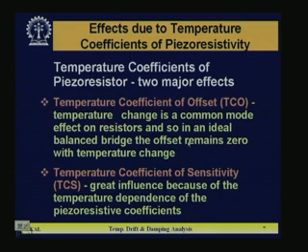Now, the offset is coming for what reason? All the 4 bridges we found there are total 8 resistances, and we assume that under no stress condition all the resistances of the 4 bridges will be the same. So, output voltage will be 0, the bridge is perfectly balanced. That is in ideal condition, but in practice all the resistances will not be the same. Even if they are the same, you are making interconnection lines, so those lines will add some small value of resistance. There are contact points, they will introduce some resistance, as a result of which the effective resistance of the arms may not be exactly the same, and if it is not exactly the same, even in the 0 stress condition you will have a certain output voltage.